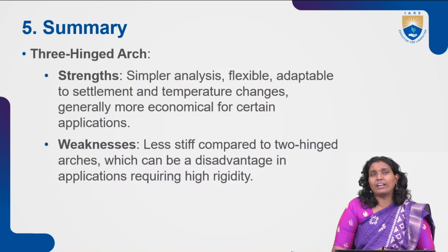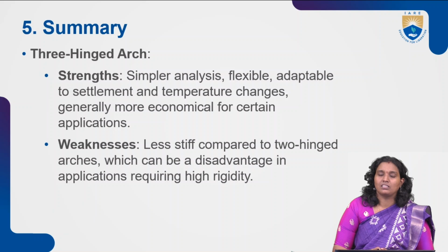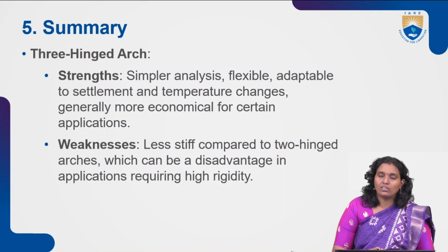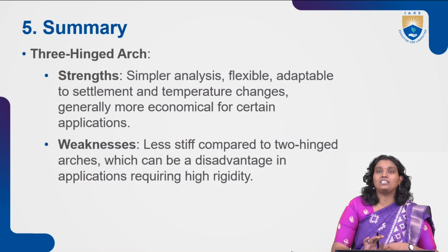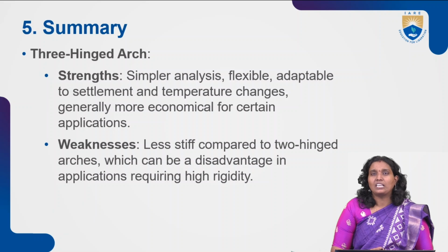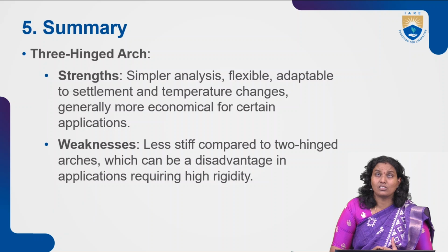And the overall summary of this lecture is, in three-hinged arches, the strengths are these. It is a simple analysis because we get the unknowns by using the statical equilibrium equations. It is flexible because the crown hinge is there, so that gives flexibility. Because of this, it can withstand settlements and temperature changes. Generally more economical, with less cost because we are using less material and less labor. So there is potential cost saving, and that's why it is more economical for certain applications.